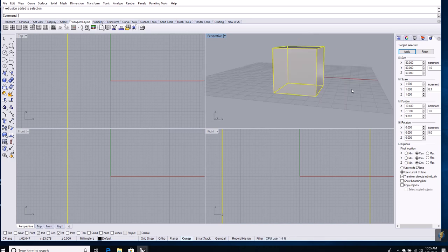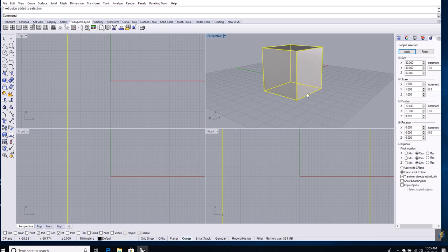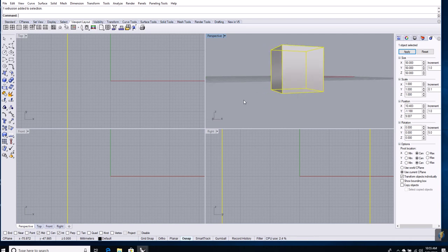You can start to do some operations to change this up and manipulate it and decide what you want to design. Okay. Now, the other thing you'll notice is that by default, the ground plane here in the perspective view is the midpoint of the cube. So I want to move it up, and so all I have to do is go to the position entry point for